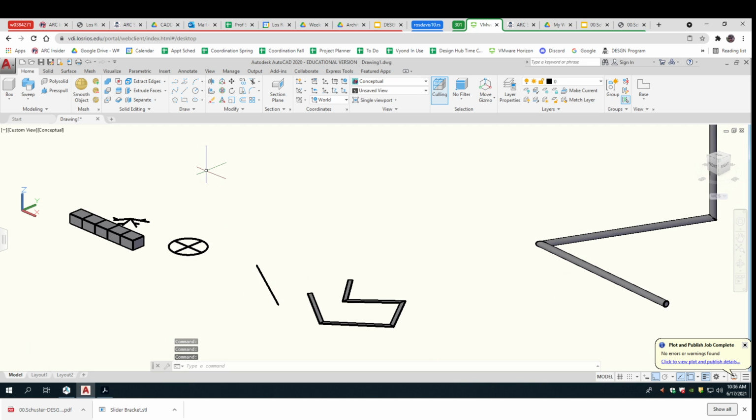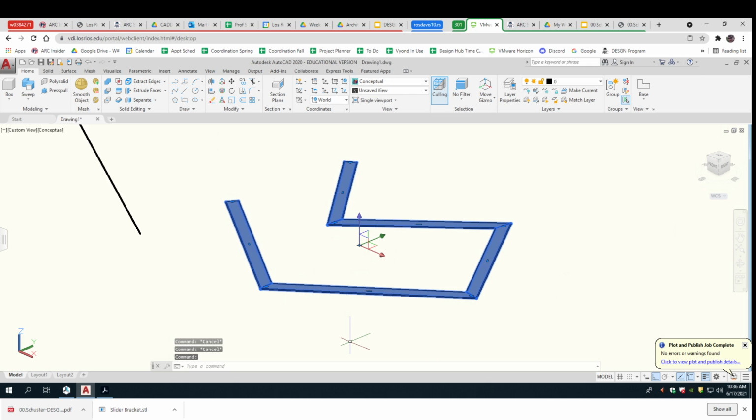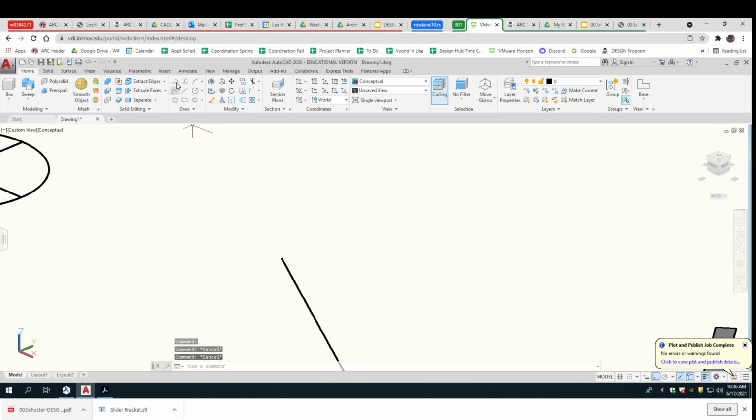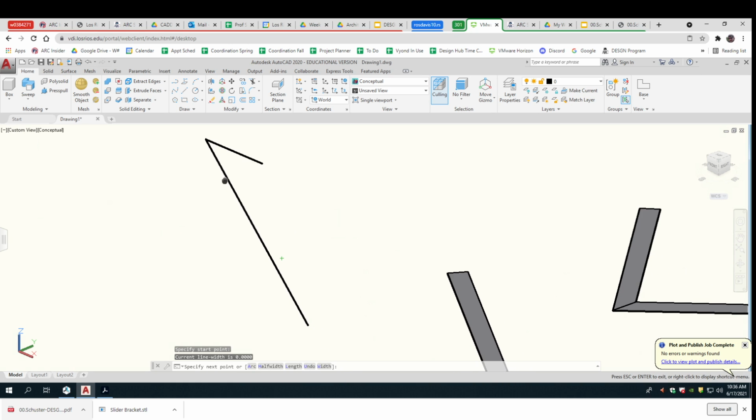Did that make sense, though? The difference between line and polyline is that it's treating this as one object. So what you do to any one piece of it, you do to another piece. Okay. One of the main ways that we do this is I make a polyline and I'm going to do the width command, and I'll start at 0 and I'll end at 2.